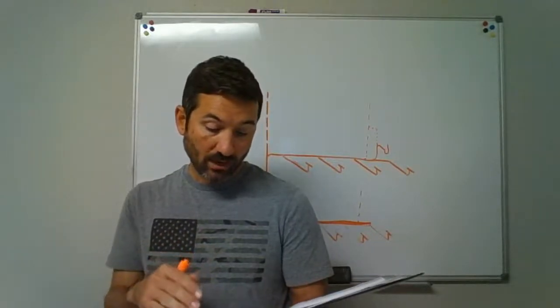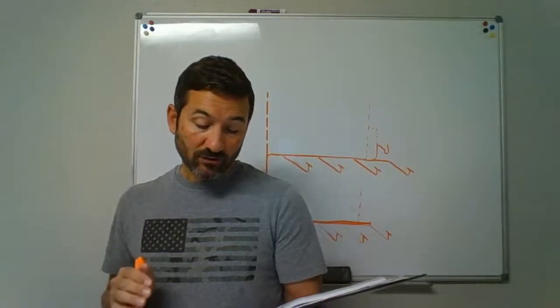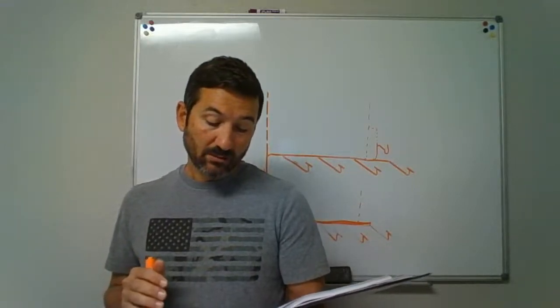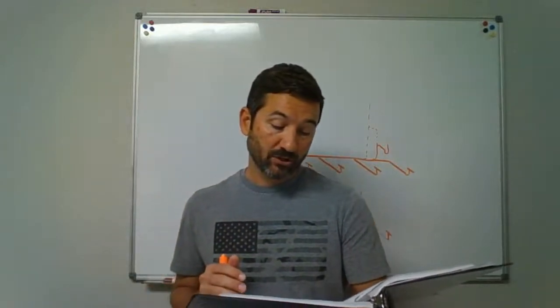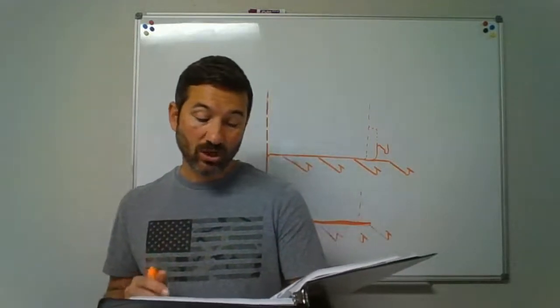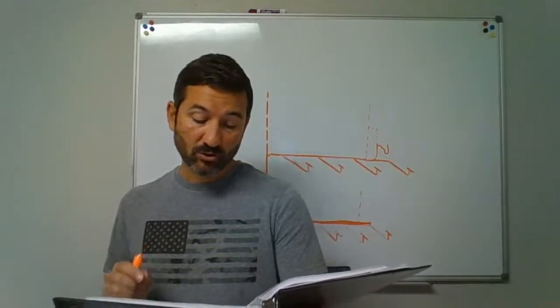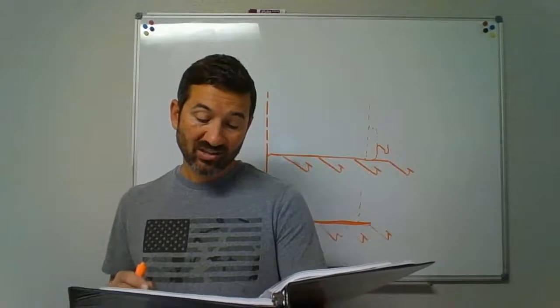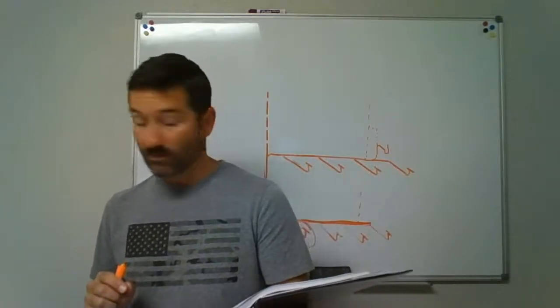Just kind of going down through there. Section 916, island fixture venting. It's got some limitations. Island fixture venting shall not be permitted for fixtures other than sinks and lavatories. Residential kitchen sinks with a dishwasher waste connection, a food waste disposer, or both in combination with the kitchen sink waste shall be permitted to be vented in accordance with this section.